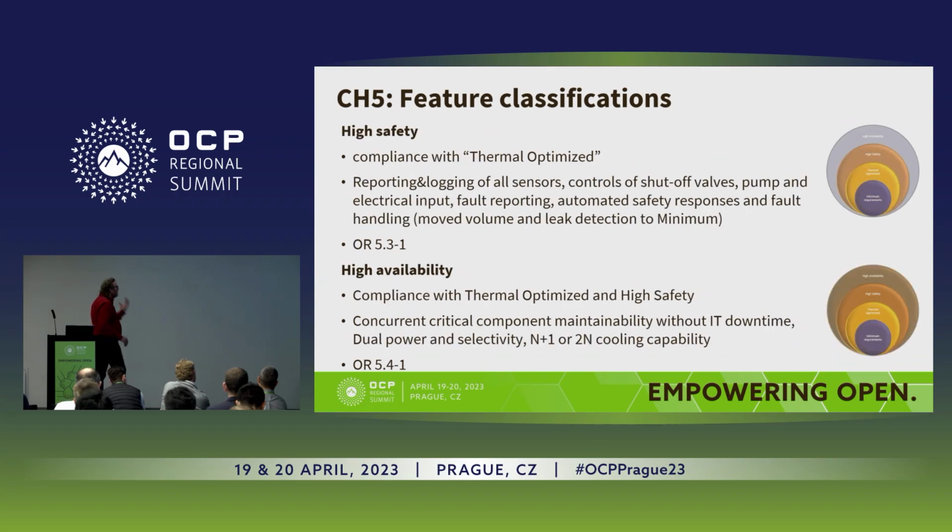A high safety classification means that you comply with everything that is in thermal optimized, so you must also be thermal optimized. High safety comes on top of that with an additional requirement for full reporting and continuous logging of all sensors. And you should have controls to shut off valves and pumps and also electrical inputs.